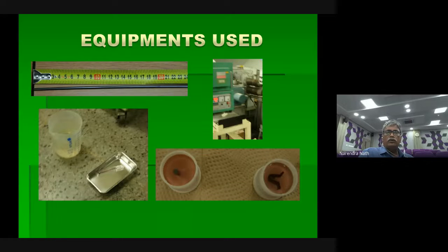This I think everybody knows. You see, after sealing, after closing, then putting inside the furnace, after treatment we take it out. Now we have to break this. The quartz tube is going to break, and you will get a fine titanium nickel rod. And this is the rod we used. These things are for metallurgical sample preparation for SEM to study microstructures.